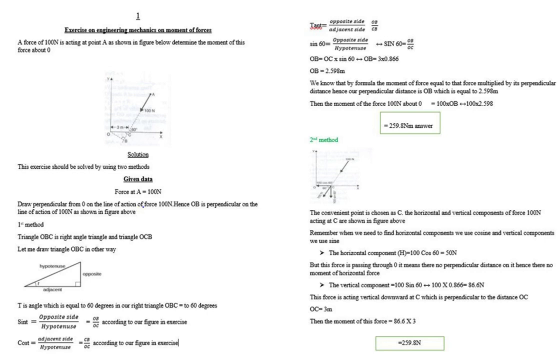Then, the direction of the moment depends on the direction of the force. We have clockwise moment, which I consider as negative. There is also counterclockwise moment, which I consider as positive moment. There is a principle of moments. For an object in equilibrium, the sum of all clockwise moments equals the sum of all counterclockwise moments.